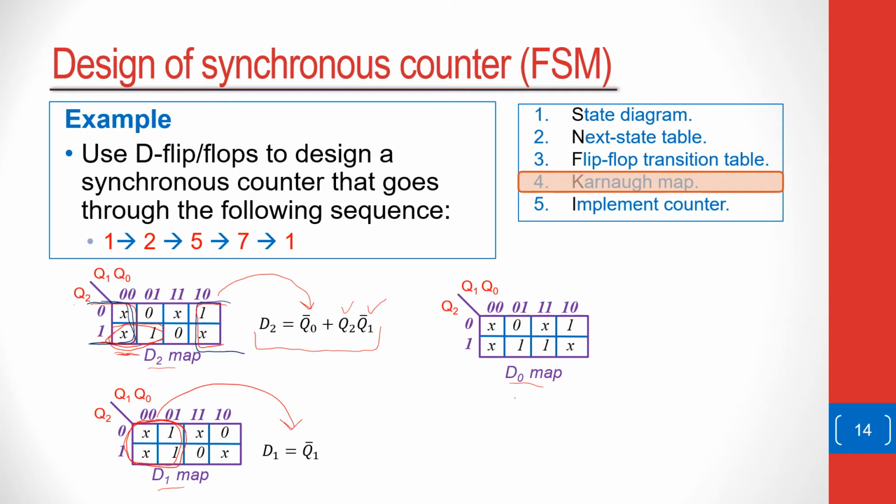And for the final logic here, as we try and create the biggest group, we can encounter a group of 4. Remember, you can't do a group of 6 here. It has to be a group of powers of 2, and then you can make a bigger one here as well. Then you'll have encompassed all the ones. Remember, we care only about the ones if you are doing the sum of products.